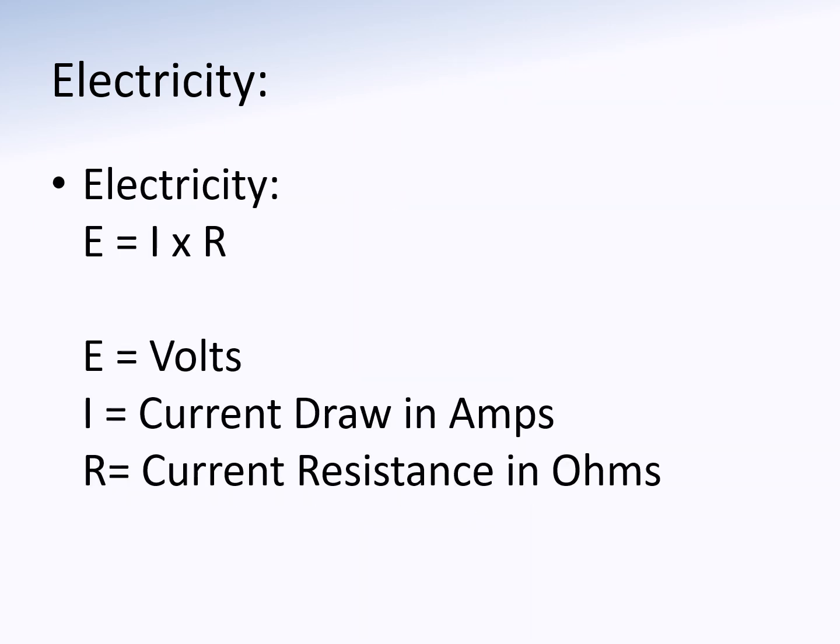One of the more popular equations used in electricity is Ohm's law, right? It is probably the most fundamental equation in electrical circuits. So you have E equals I times R. E is the equivalent of volts, I would be amperage, and then you've got R, which is your resistance, and that's measured in ohms. You could say that the push, or the voltage, is what's needed to move electric current through a resistor, and that depends on how much current you want and how much the resistor will resist. So let's go over an example of that.